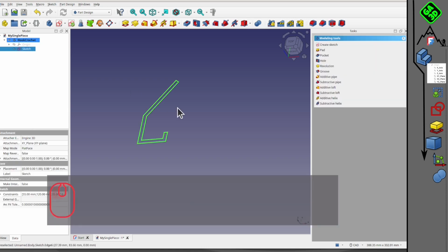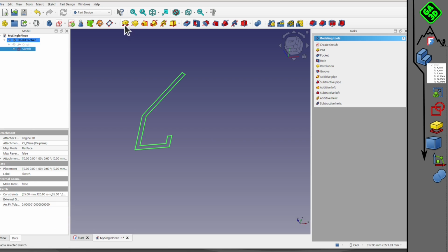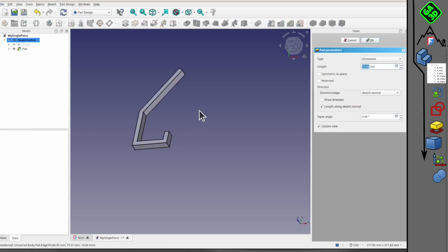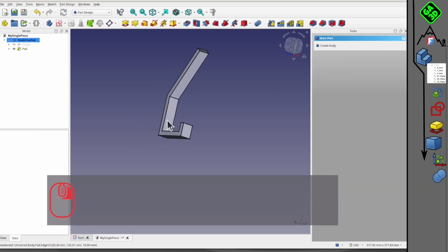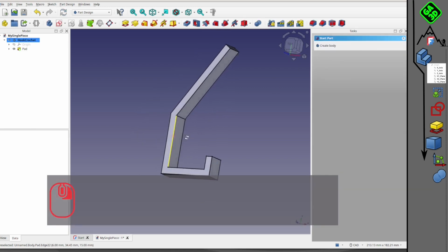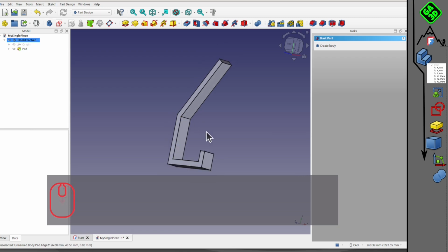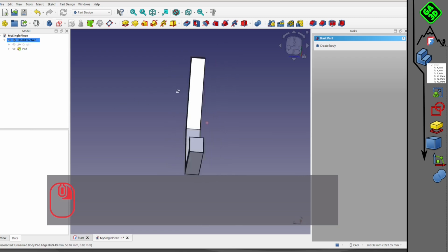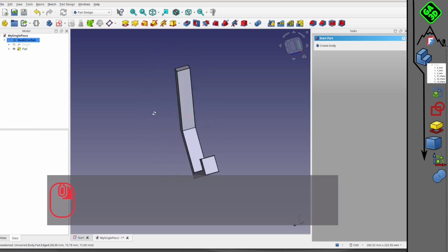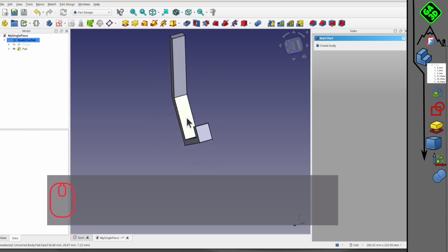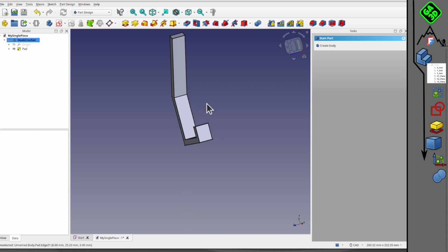Now, more than just doing the additional operations, I want to add a hole to put a screw in. We're going to put this right in the middle. Then we can add some radii, some chamfers. And we did the workflow for the single piece. So here, to add a hole, you can simply click on the face on which you want to add that hole.